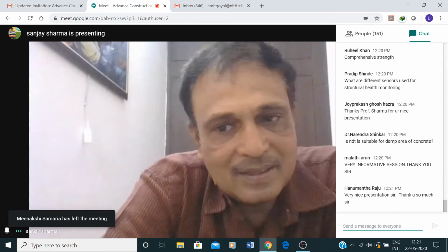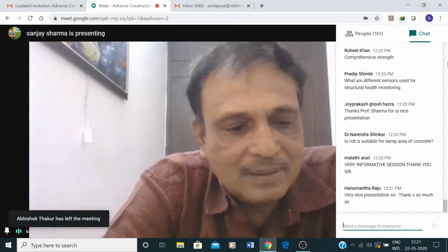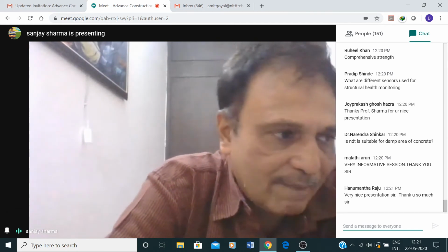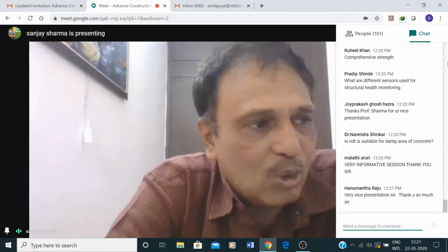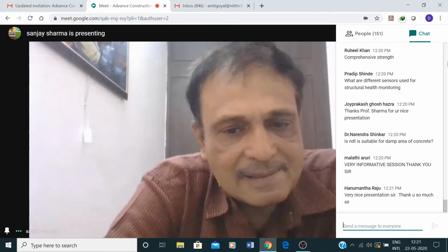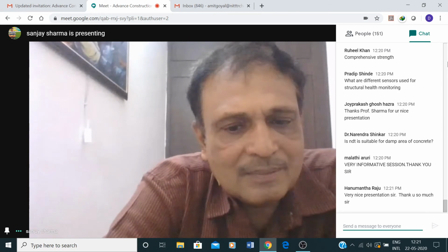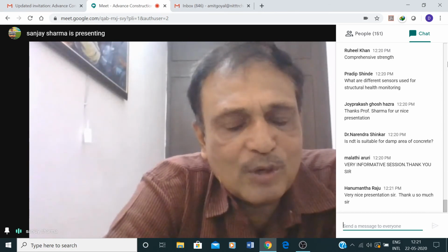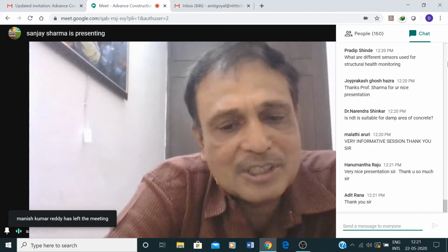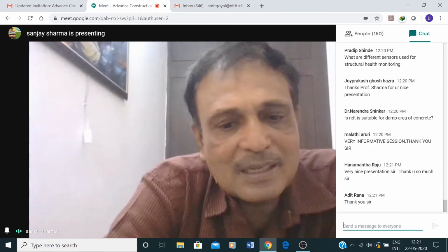Okay, sir, please comment on NDT of mortar joints in masonry. If you want to determine the strength in masonry, you can use this P-type hammer for this purpose. Okay, sir. So how can we calculate dynamic elastic modulus? You can use even UPV for that. If you know the strength and you know the parameter also, you can find out the elasticity using ultrasonic pulse velocity.